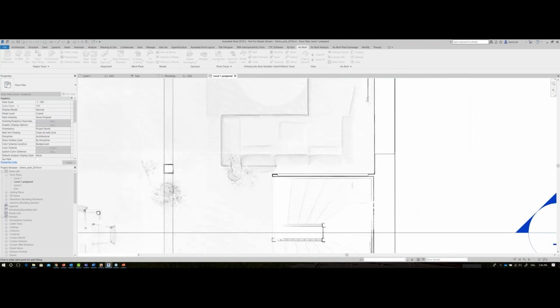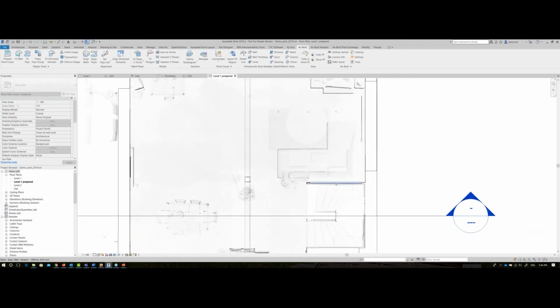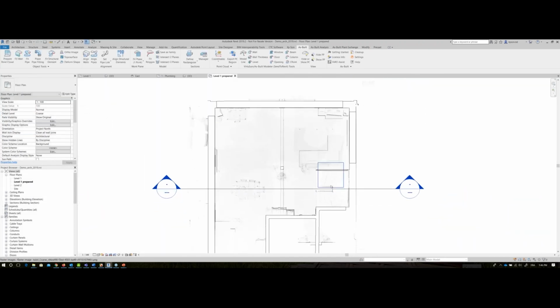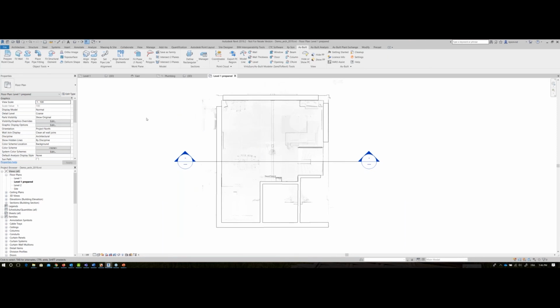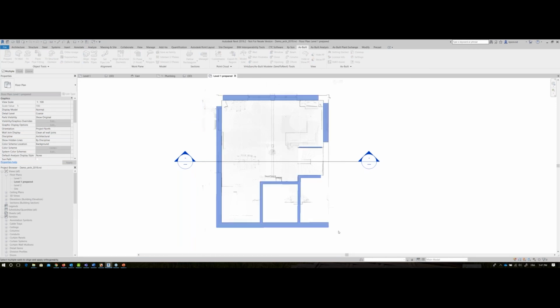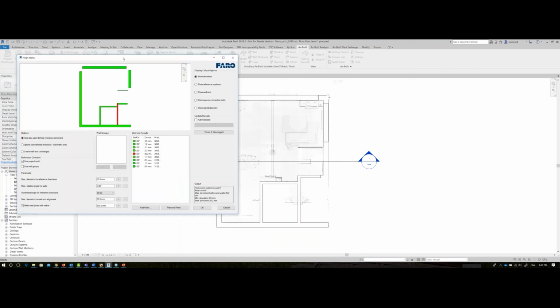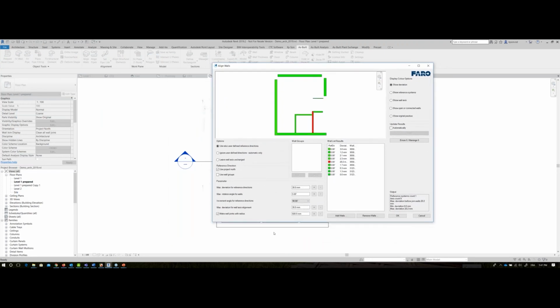So once everything is created, you see here, actually my walls are not closed. So you have two choices here. You can close them manually, or you use the other tool that we call here align the walls automatically for me. So I'll be able here to ask those walls to be closed automatically based on some calculation. I'm selecting my walls and I'm choosing my parameters here.